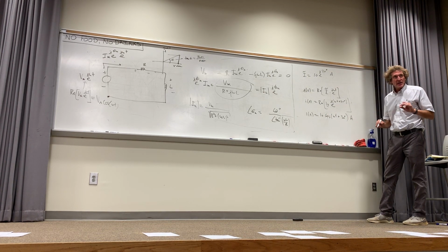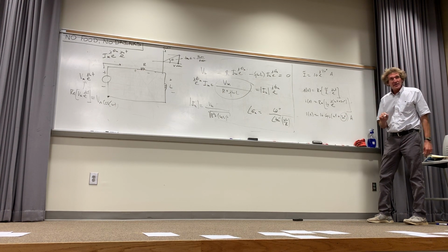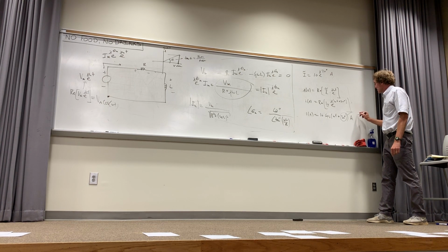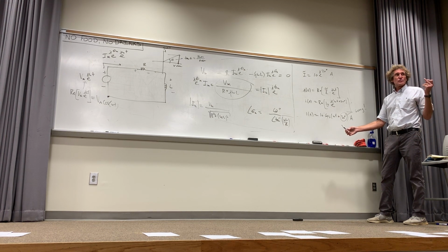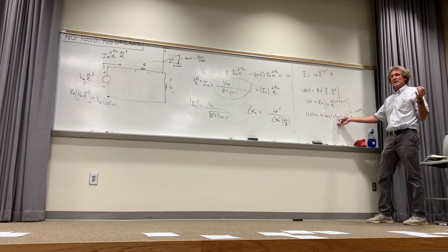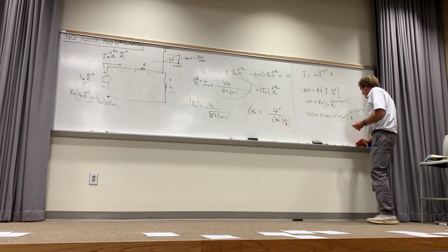But I gotta say one other thing, heed my warning here. You see this right here? Circle that and say something wrong. Here's why you don't put 30 degrees in here. Almost without exception, ωt has the units of radians. Follow me? This is the units of degrees. You always take that and turn it into radians. Now 30 degrees is what? It's π/6 radians, isn't it, class? Isn't that right? Sure, so you put π/6 here.